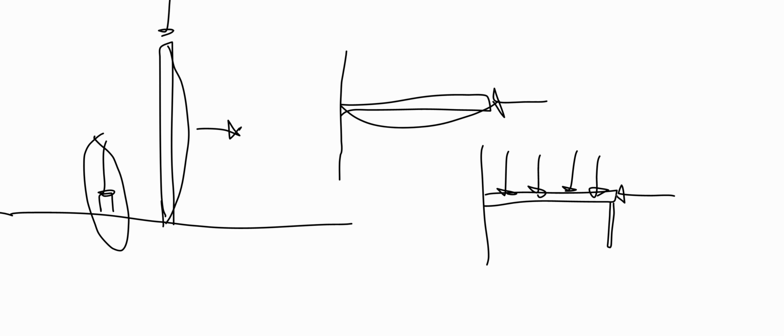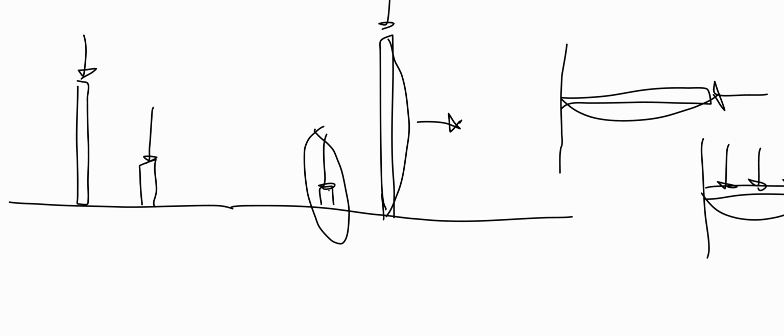Even though the weight's really coming in from the right, once it bends, it's going to act as if all that weight was instead trying to make it bow down and buckle like a beam. And that's going to make it fail a lot quicker because these things are normally not designed to be beams. They're designed to be columns. So that's why buckling is a problem. Now, that's for a tall, skinny thing.